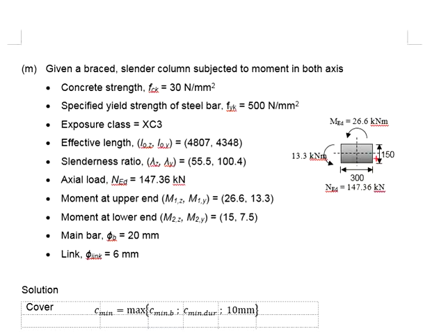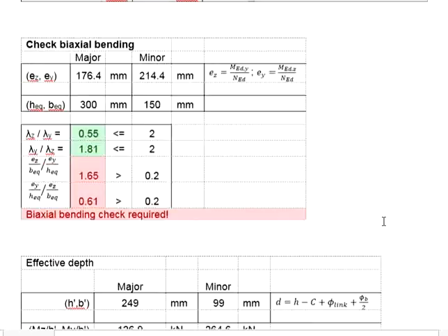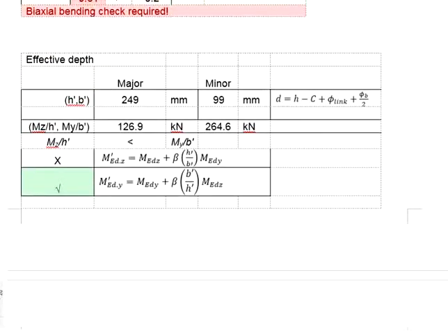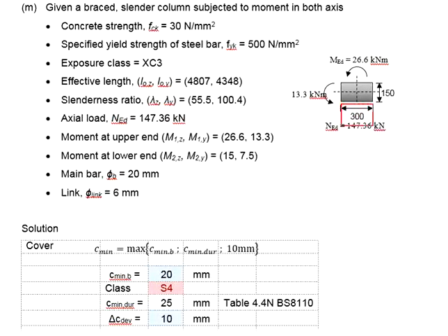Normally, we will enlarge the B section, since based on the calculation here, the minor axis appears to be more critical. Enlarging the H section will still leave the minor axis more critical. From a practical point of view, ultimately the amount of reinforcement bar required will still be governed by the minor axis.